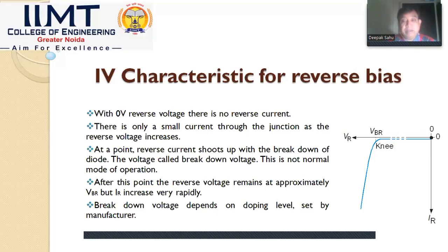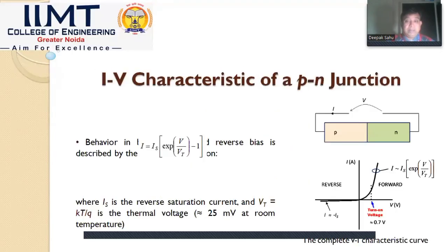But we have to always see the data sheets as to whatever the breakdown region is, and accordingly the battery system or maximum applied voltage has to be chosen by considering the breakdown region, because in forward bias we can limit current by adding an external source. But if the reverse breakdown region is not considered and the application we are creating has a large voltage value, then it could result in the destruction of the diode device.